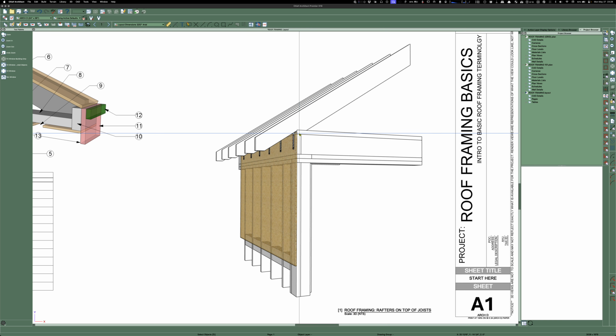Sometimes they would subfloor like 24 inches in or 48 inches in, and then run a 2x6 plate down. And that was awesome for insulation, which they really didn't need. But it also made it so if you had attic space, you gained all this right here. So I thought that was an interesting way to do business.